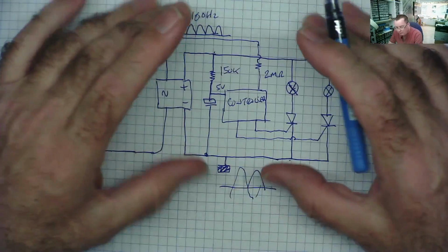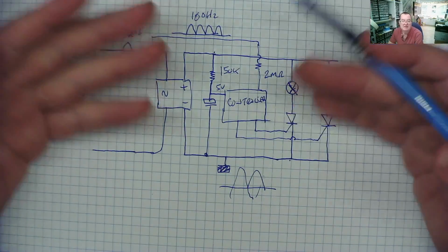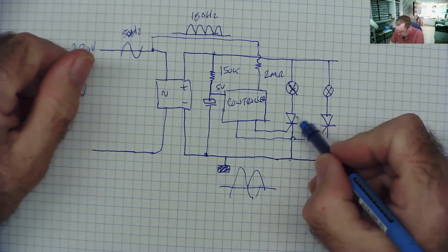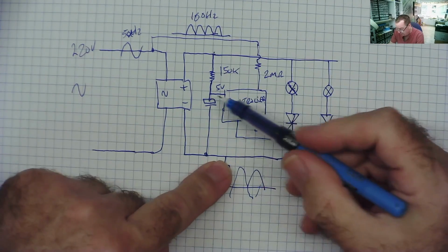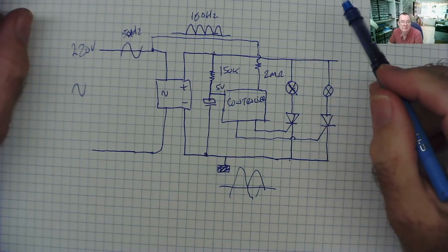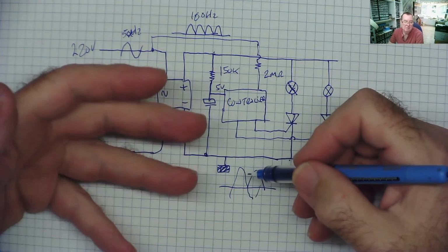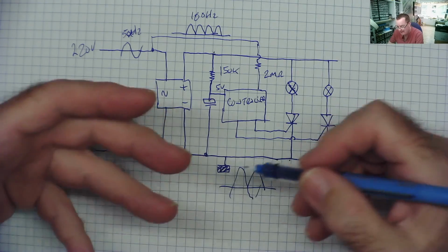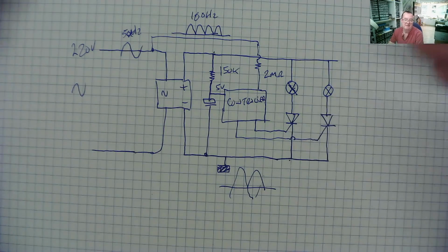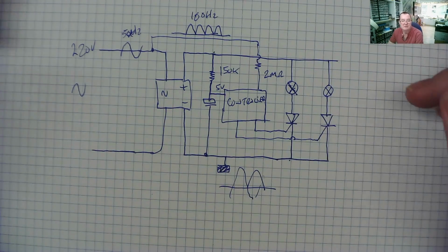So all this circuitry, as I say, is at high voltage if you stick your finger on it. But if you use your voltmeter from here to here, it's 5 volts. Don't let hot ground confuse you. It ain't safe for fingers. It's not finger safe, yeah? So that's the other sort of arrangement that you can find.